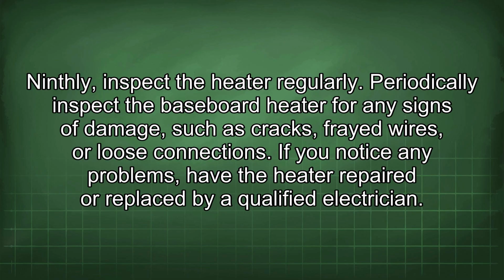Ninthly, inspect the heater regularly. Periodically inspect the baseboard heater for any signs of damage such as cracks, frayed wires, or loose connections. If you notice any problems, have the heater repaired or replaced by a qualified electrician.